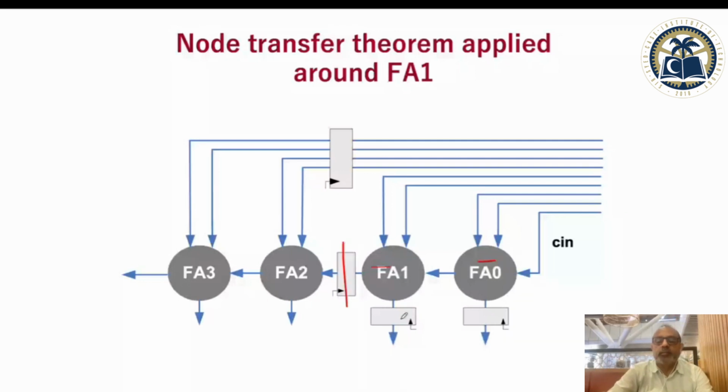And these are there for synchronization: all these inputs are to be delayed, all these outputs are to be delayed. So this full adder will have one cycle delay. Once you say add this, you will only see the result in the next clock cycle. Because of this, every path sees one clock cycle delay going from input to output, and you will get a fully synchronized output.